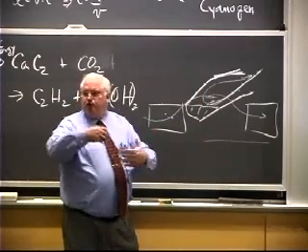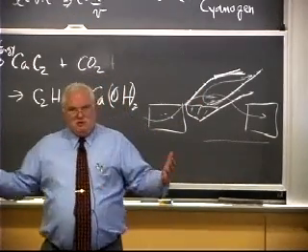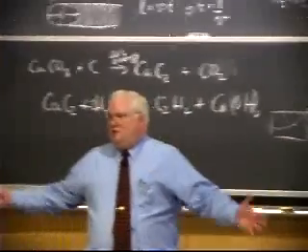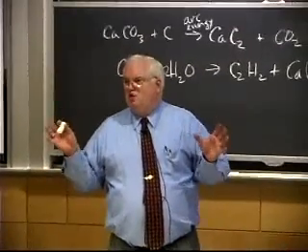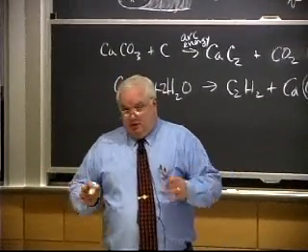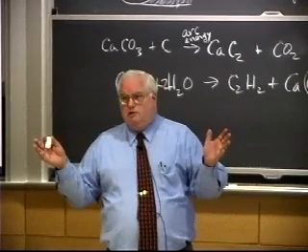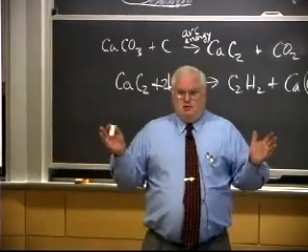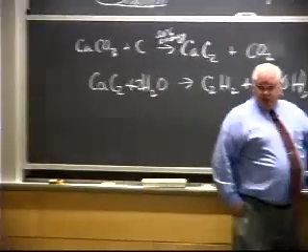And so you would reverse about 2 or 3 times a day. You would reverse the flow of gas through these football field size brickwork lattices, and you had huge thermal masses that were basically storing the exhaust gas heat. And that was the basic open hearth, which was the way of making steel until, what, the mid-60s. So from 1900 to the mid-60s, you had huge basic open hearths.